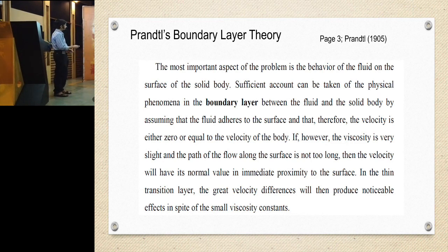The most important aspect of the problem is the behavior of the fluid on the surface of the solid body. Sufficient account can be taken of the physical phenomena in the boundary layer between the fluid and the solid body. So that's the layer which is between the far fluid and the solid body. By assuming that the fluid adheres to the surface, okay, so that is the no-slip condition that you must have